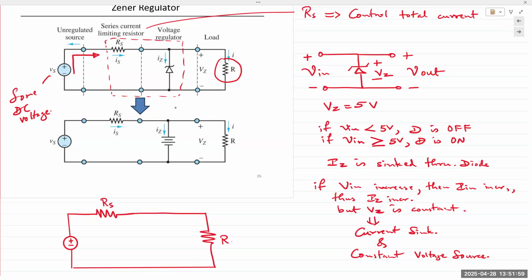What do the two resistors create? What kind of circuit? They're in series, so what happens to current? It remains the same. What happens to voltage? It gets divided. So it's a voltage divider circuit.